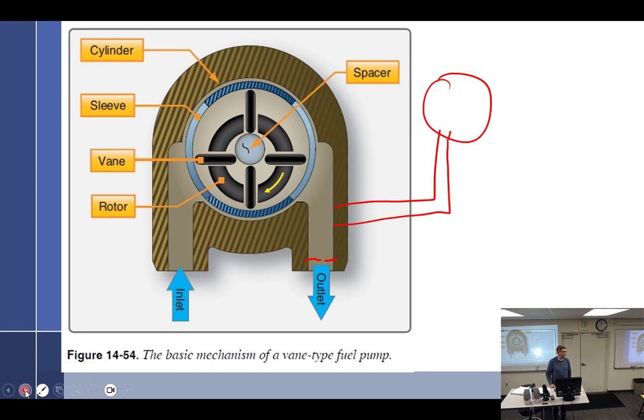That's where you talked about that one story, where one of your friends said, when you asked how long they ran the boost pump, yeah, like 30 seconds. Oh, it wasn't more than 30 seconds. Wasn't more than 10 would have been the right answer. Especially if you had a fuel flow indication.